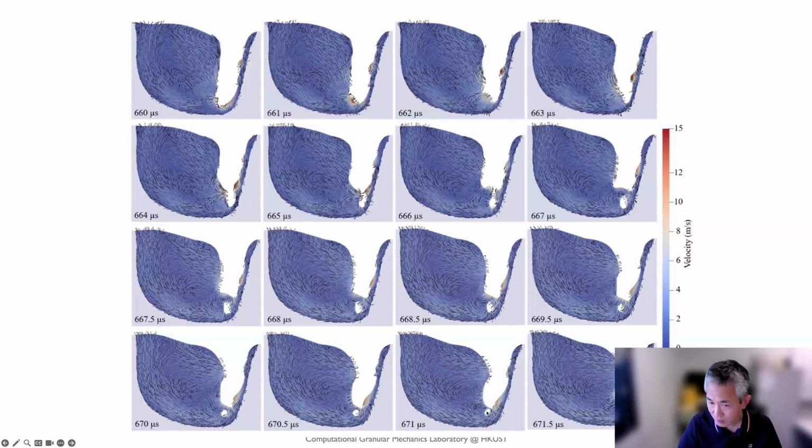Okay, but sometimes this pore itself, due to this metal pool liquid motion, can move back to the keyhole and then merge with the keyhole again, such that some keyhole pore can be merged by the keyhole itself, and so it disappears. And so in this way, this is the whole process. This one now is recovered by this keyhole, and then there's no keyhole pore generated here.